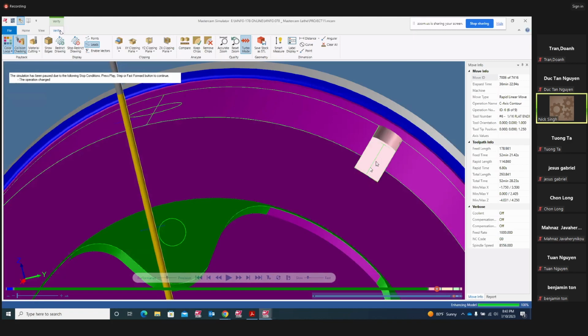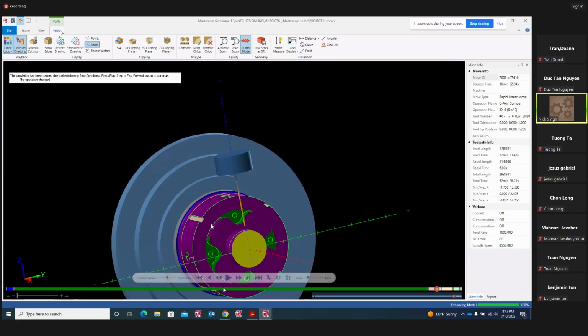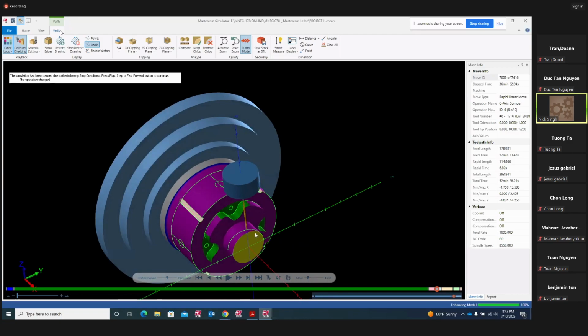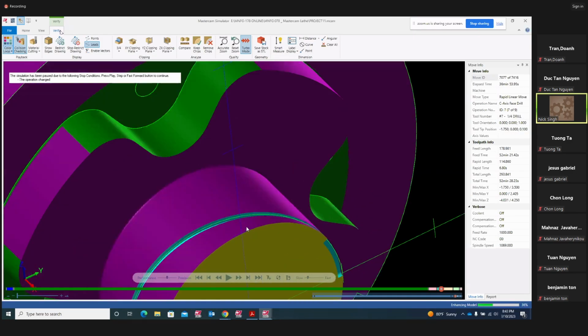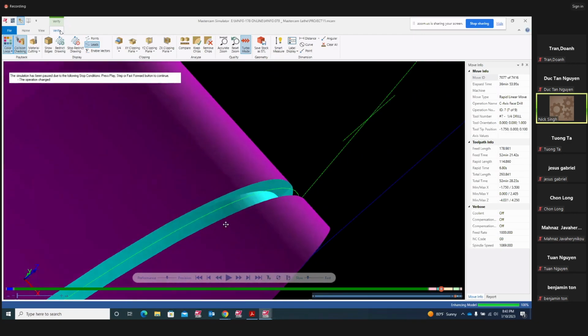So you're going to pick these lines for your contour. 4 lines. That's why we have drawn these 4 lines right here. And there comes your Z-axis. This is what we are talking about, 2 inches diameter, and we're going to go about 0.050 deep. That's going to cut this slot right there. Look at that. That slot is right here. This guy right there.